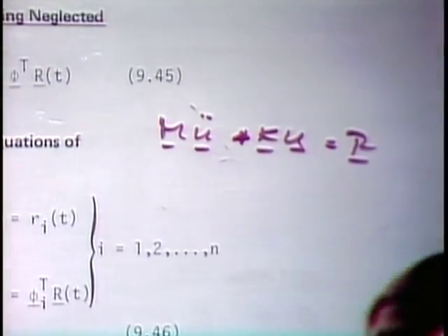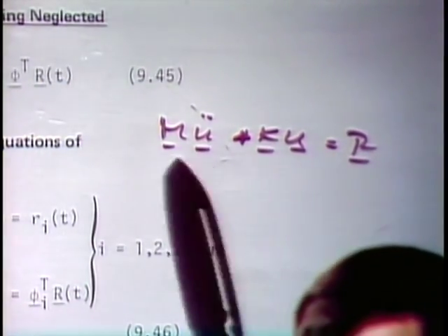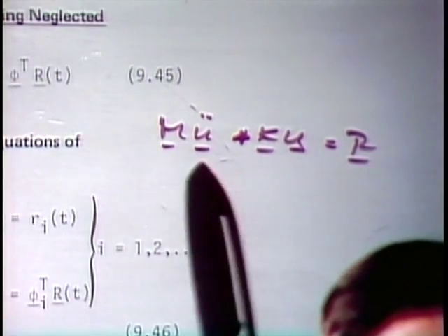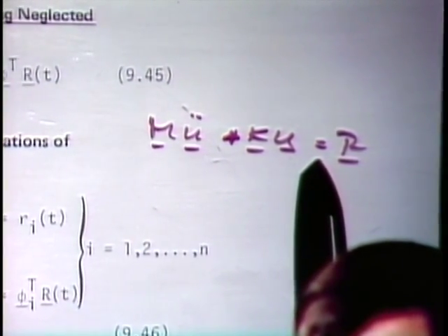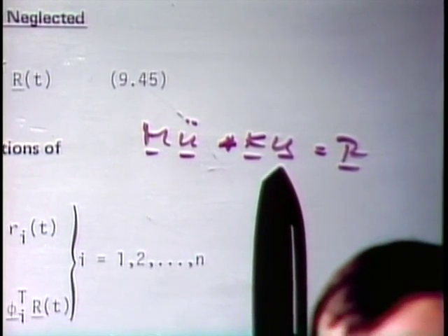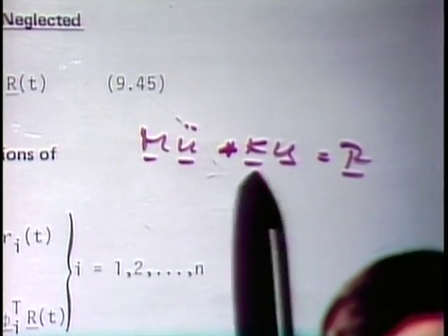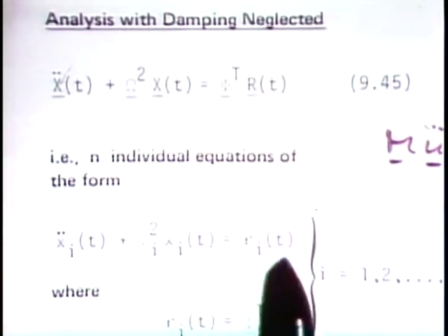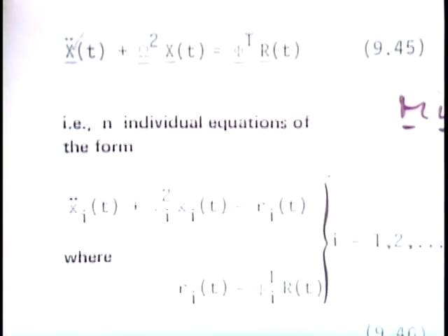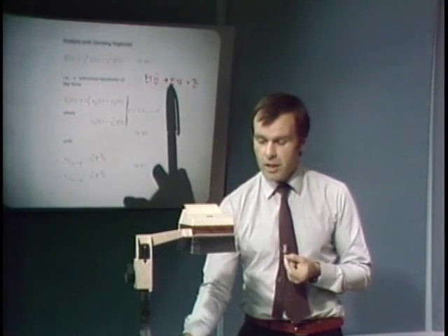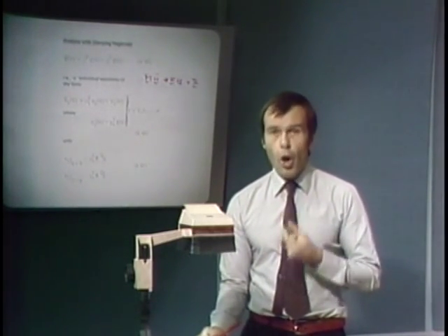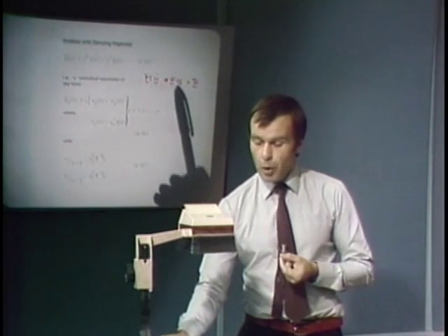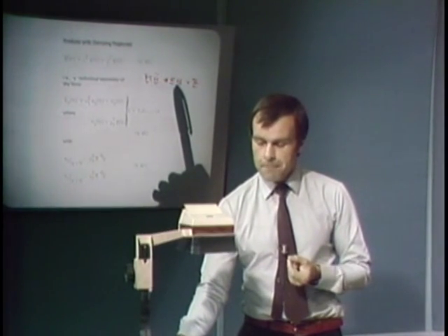In other words, whether we apply the Newmark time integration scheme, a direct integration scheme, to this set of equations with the initial conditions on u and u dot, or apply the Newmark direct time integration scheme to this other set of equations, with these initial conditions, we obtain exactly the same response, provided we use the same time step, delta t, in both integrations. There has been no assumption so far. All we have done is a transformation from the u displacements to the x displacements.